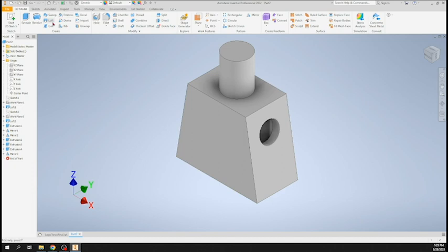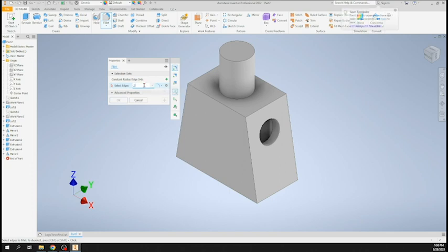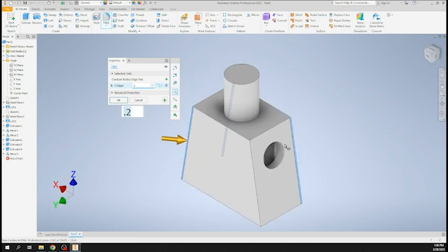All right, we just have some fillets to do, so let's take care of the fillets. So use our fillet feature. Oh, where did it go? Where did my fillets go? There it is. Click on that. For the first one, I want 0.2, and I'm going to select the sides. Okay, all the sides, all the way around, 0.2. Okay, if I have to spin this around, I will. Okay, all 4 sides at 0.2, and the head as well. All right, and hit OK.